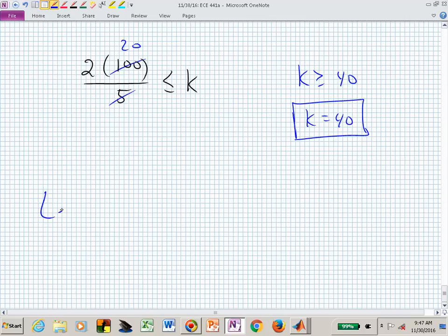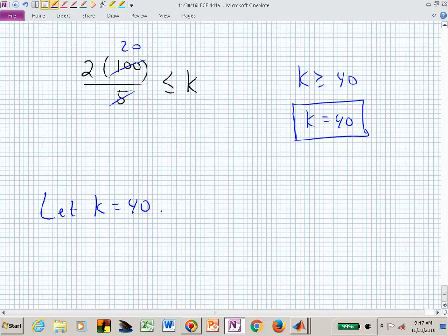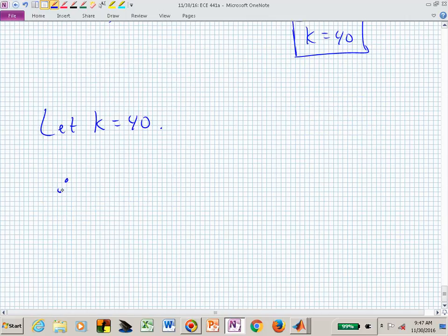So now we have K of 40, and we've actually succeeded with our interview question. So now if we let K equal 40, we now have a G of S with a fixed gain. And what structure is this controller in? Time constant or pole-zero? Pole-zero.